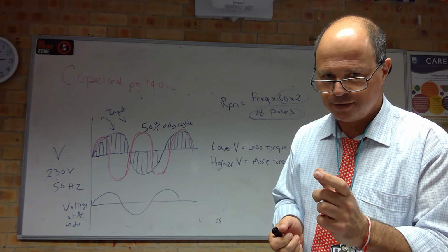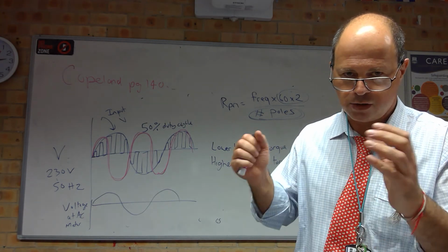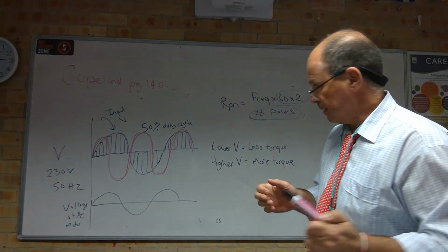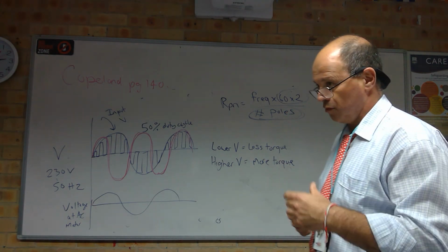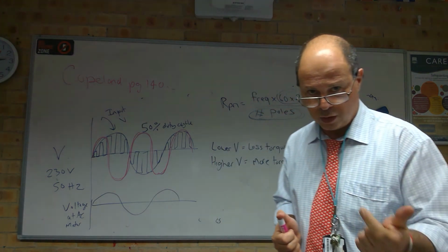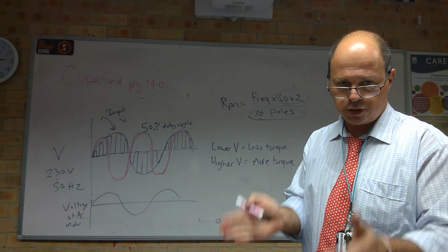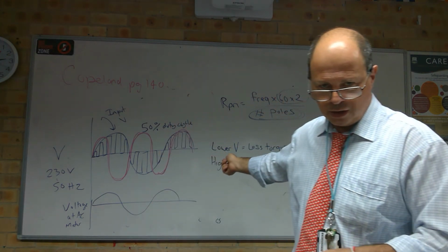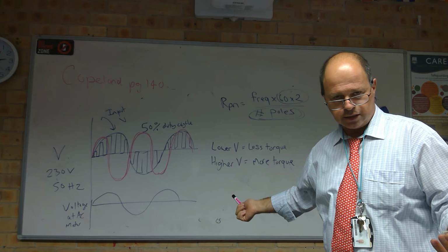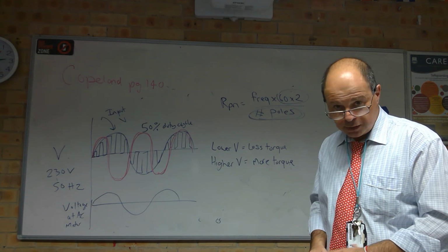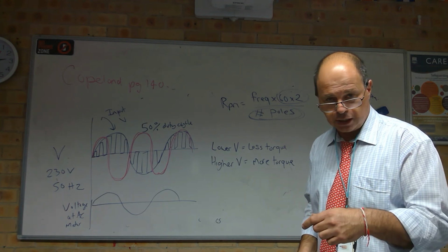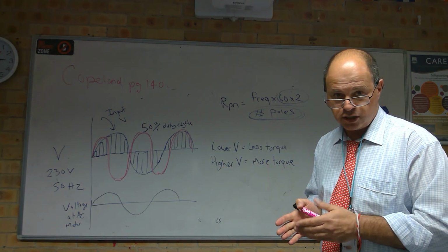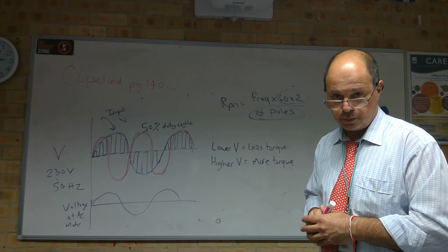They chop up the mains coming in, and that's why you're able to use a smaller transformer in your more modern electronics. So that is variable frequency drive with pulse width modulation to control speed and torque in an AC motor. And earlier on we talked about just pulse width modulation for a DC motor. Hope that helps. Watch and do some more research online if you like, but you do now know what pulse width modulation is and how it controls the speed of a motor.